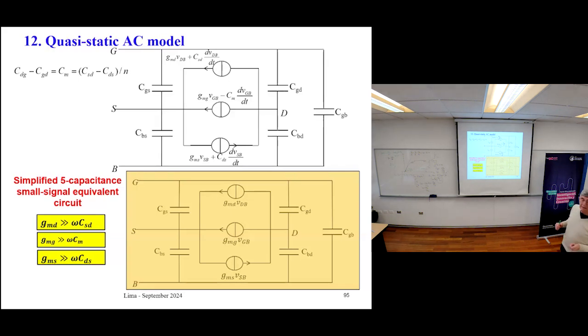you have to make the DC analysis before the AC analysis, of course. You should know the operating point of the circuit in order to calculate all these parameters. Okay? This is a big issue. First of all, you have to solve the DC equations of your device, or to put this device in a simulator and find out what is the DC operating point.